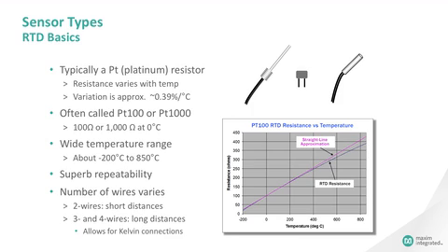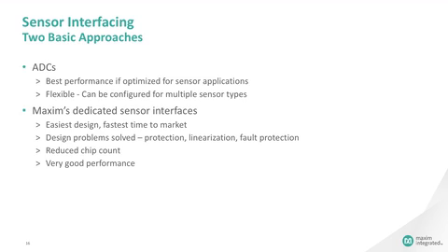These extra wires are used to separate the excitation signal from the measurement signal, allowing either partial or full Kelvin measurements. This serves to eliminate the effects and errors associated with lead resistances. There are 2 basic approaches to acquiring the signals using RTDs or thermocouples.